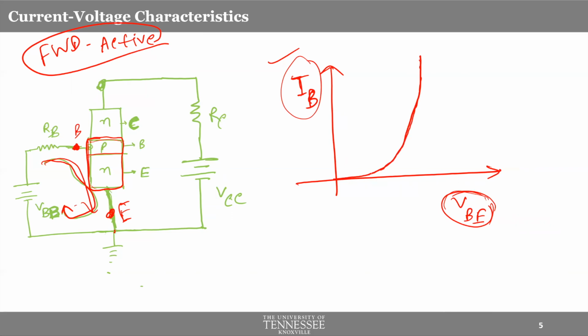Now, there is a catch. Even though it looks like a PN junction, there is another terminal which will definitely interact with the PN junction we're dealing with in the input circuit, and that's coming from the collector. We will also have to see what happens when you apply different levels of collector voltage to this BJT. Say this graph was for a specific value of collector emitter voltage. We have a collector, an emitter, and a voltage across the collector emitter side.